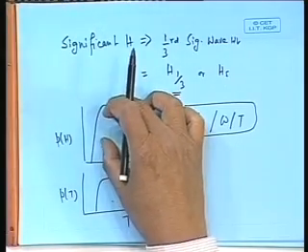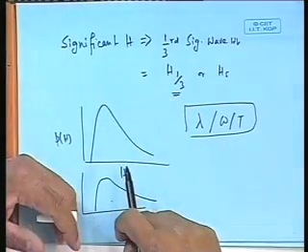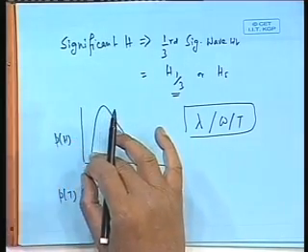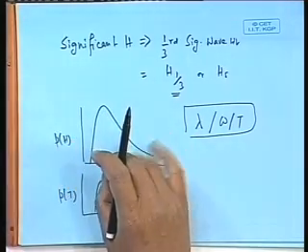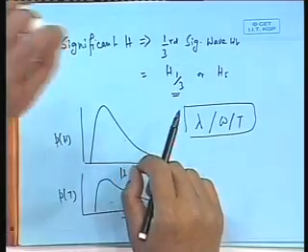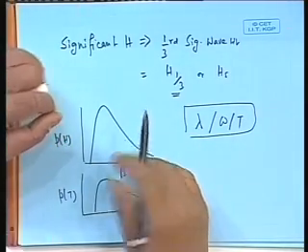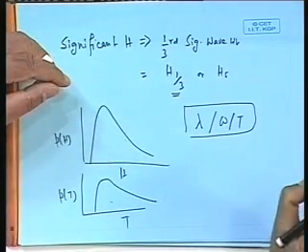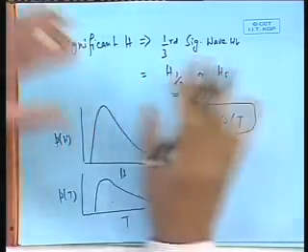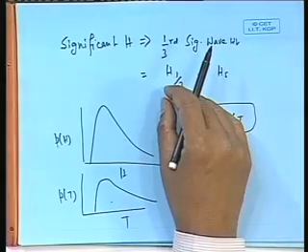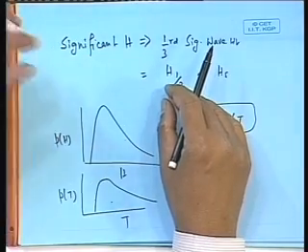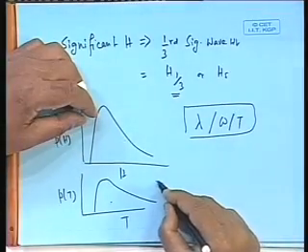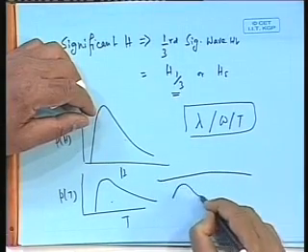Here I am telling how many times this height has occurred, here I am telling how many times this length has occurred, but I am not anywhere telling what is that time a certain height of certain length has occurred. Because after all, occurrence of a 10-meter high, 1,000-meter long wave, with very small slope, is much less severe than occurrence of a 10-meter high, 100-meter long wave. Because one would be occurring like this wave, another is occurring like this wave.